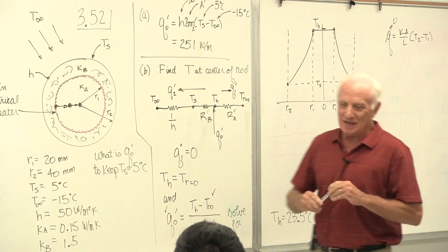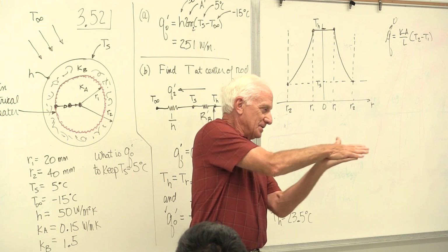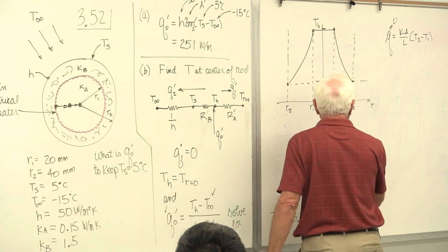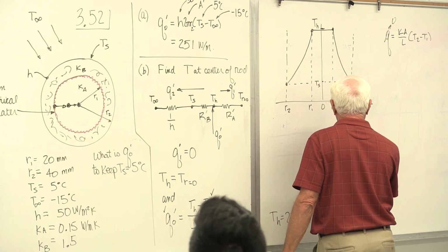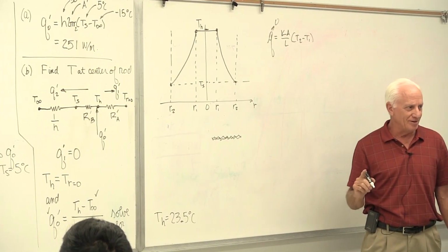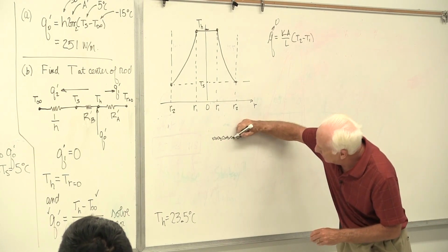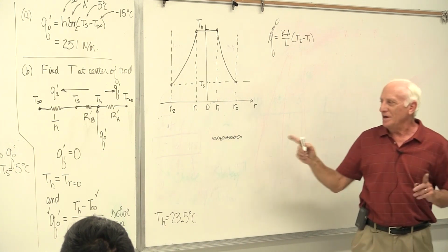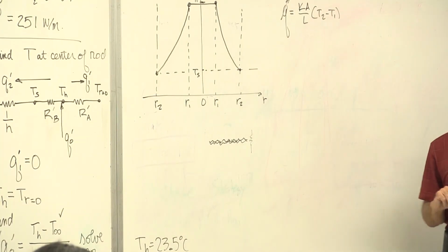Contact means when you have two dissimilar materials and you press one against the other, it's never perfect contact. There is a resistance in there. Here's the asphalt outside on the street. Here's my shoe sole. Does my shoe sole everywhere touch the asphalt? No, the asphalt's rough to the feel. There's little bumps on it. The only place there's conduction is where the bumps touch each other. If you want, you could put a resistance in here to take that into account, called the contact resistance.